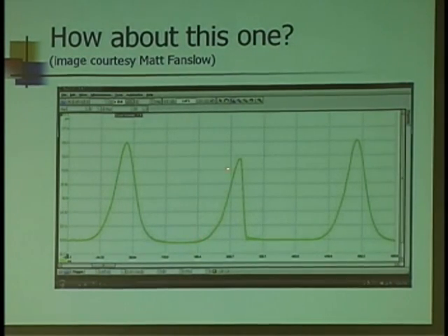And all of a sudden the pressure starts to build again. What happens at TDC, exhaust? Pushes out. Well, the exhaust valve is just starting to close right after. But what happens with the intake? The intake opens just before, right? So as soon as that intake valve opened up, all that pressure went away.